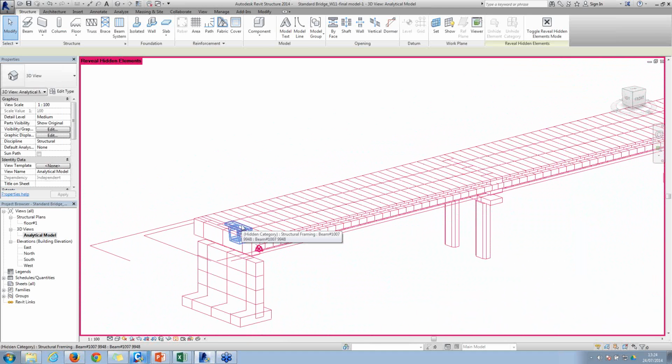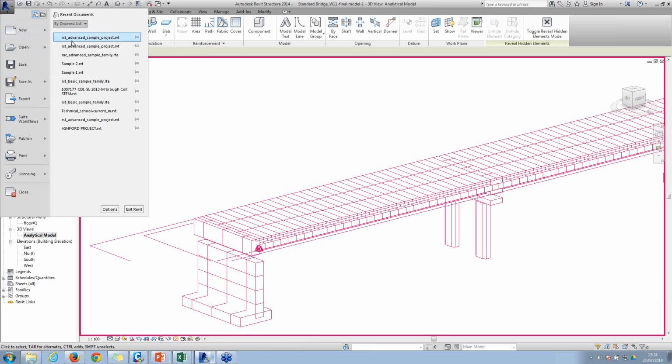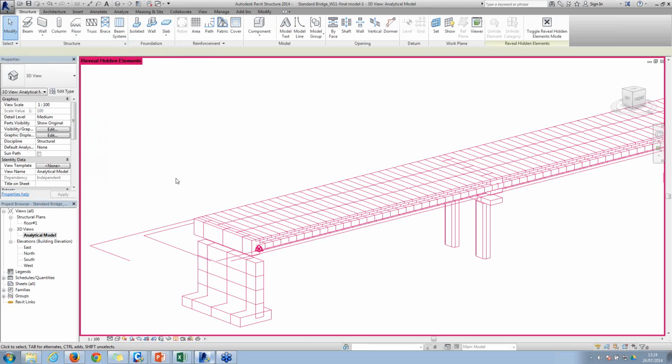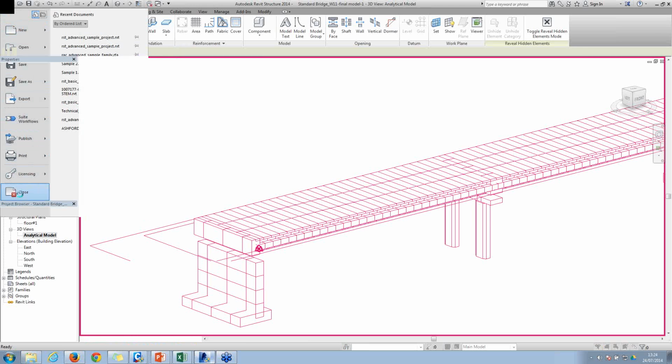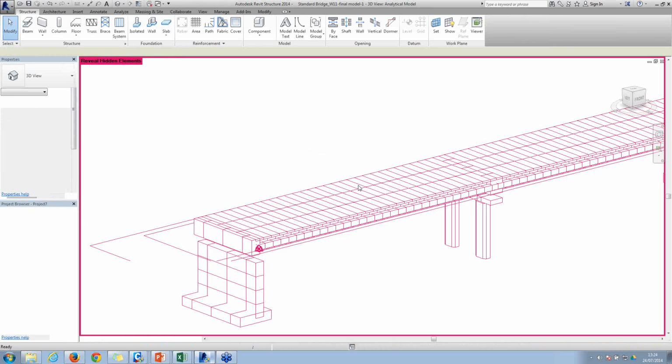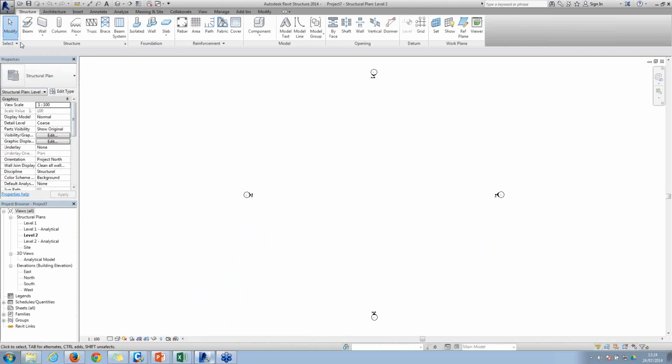It can be a plate model, it can be a grillage model, any type of model you can bring directly from Midas into Revit through IFC file format. And the other way around, if you have an existing Revit model, then you can bring that Revit structure model into Midas Civil. For this, I'll just take a general structure as an example. Okay, so I'll just close this.